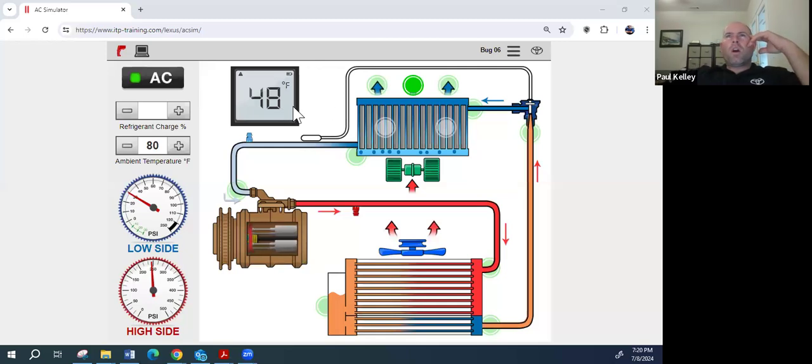If we went out to that car and that other RAV4 blew at 39 degrees and theirs is blowing at 48, now we got to look a little further, right? So this could have been an NPF. But the problem is we went and verified it. And we're like, you know what? The other one's blowing 9-10 degrees cooler. There is a problem with this car.